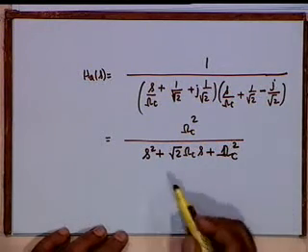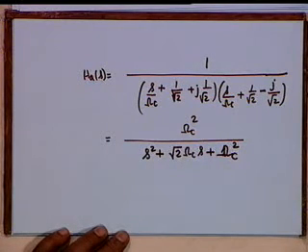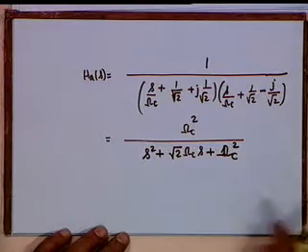The second order Butterworth polynomial is s squared plus root 2 s plus 1 if omega c is normalized to 1. Okay. Now, if we go to the third order,